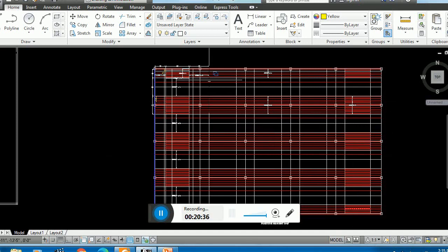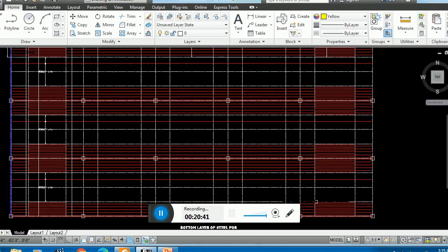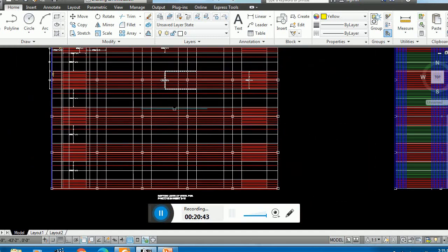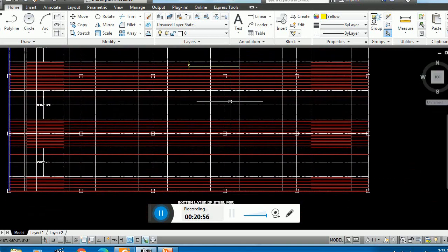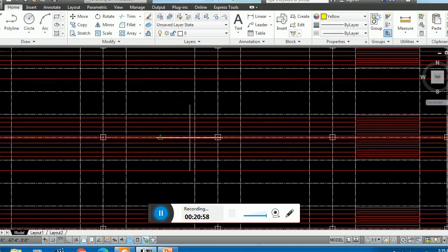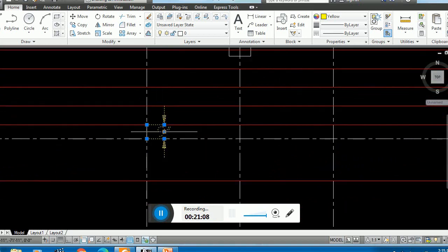Remember, in these external panels you just have to provide this extra amount of reinforcement, while in the rest of the panel you see here, this is number 5 at the rate of 12 in center to center. If you want to check it, let us check it: 1 foot. Okay, all the amount of steel will be the same. Not this one, let me check it, this one.